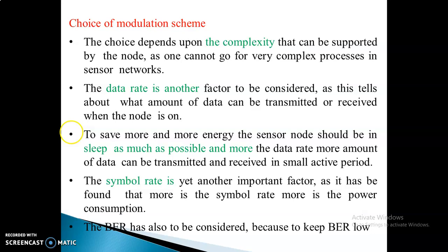Data rate is the rate in bits per second the modulation can accept for transmission, so the rate at which the user can transmit binary data. For binary modulation, the bit rate and the data rate are the same. Often the term bit rate is used to denote the data rate. Whatever term we use, it all depends on the modulation and demodulation.